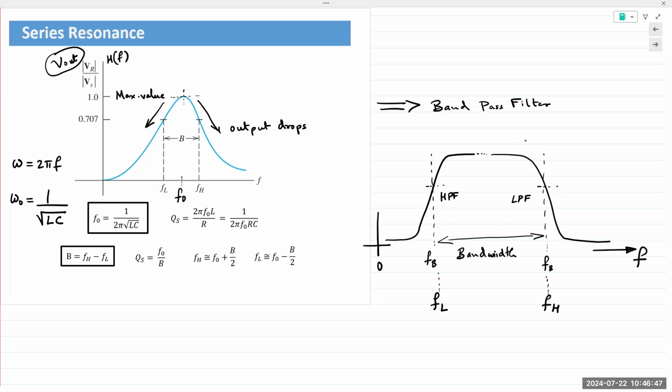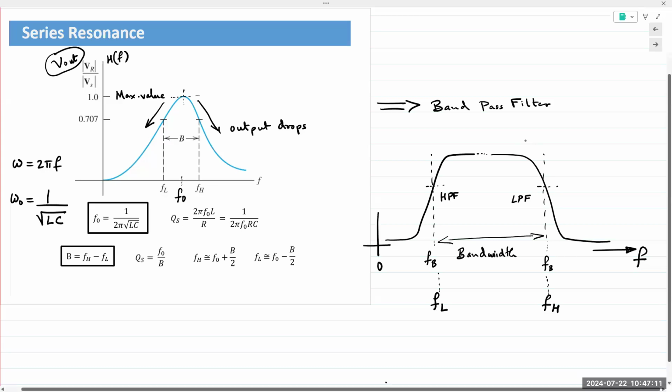Has anybody ever encountered such a situation? That's what is happening. It's interfering. So when you design a filter, you want that filter to be very narrow. If it's 107.1, you want that band pass filter to only allow the 107.1 megahertz signal to go through. Obviously, in real life, you can never make a band that looks this narrow.